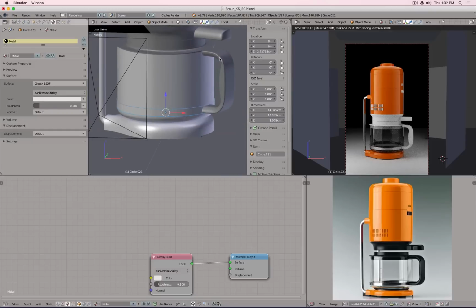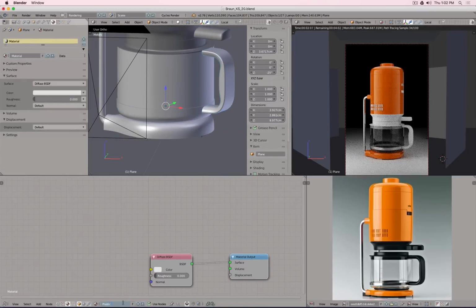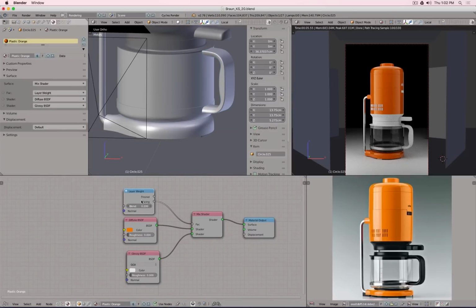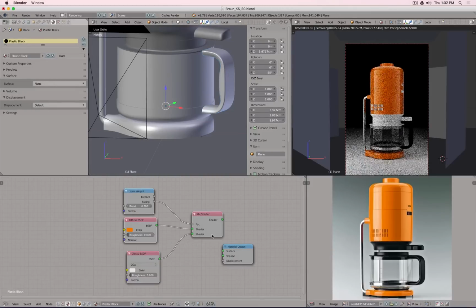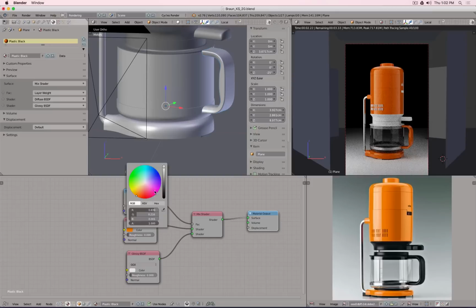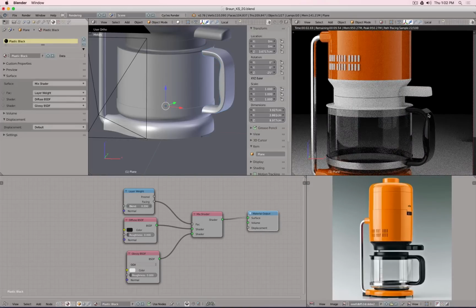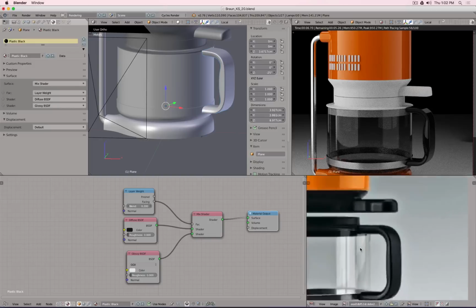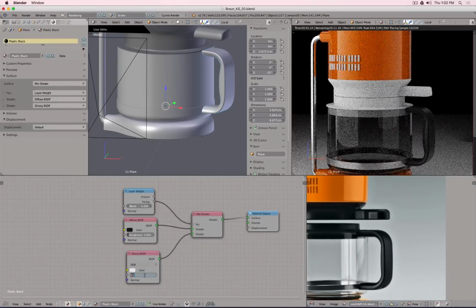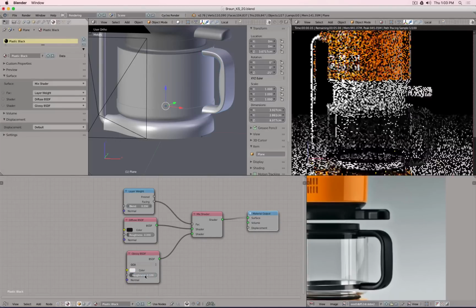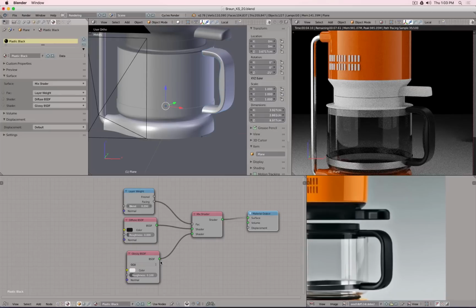Okay. Now this will be plastic and black. Could actually go to this one here and select all this. Control C, go back to the handle, delete this one, Control V, paste this in, and then make this a black material. But we do not make this 100% black, but we increase this a little bit because there's no material in the world that is 100% black. Now we see a little bit of clear reflection here, but inside the reference object we can see it's very diffuse. So 0.1 maybe. What about 0.2? 0.1 roughness. Okay, so this roughness simulates that the surface is slightly structured by simply blurring the reflection.